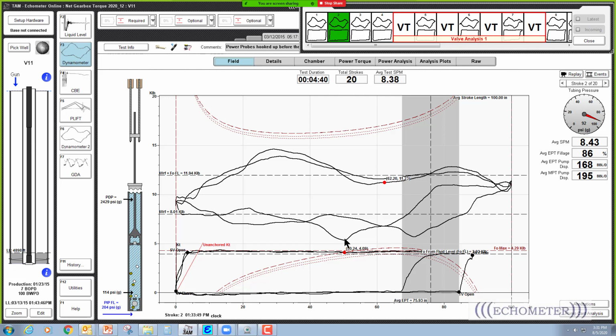So if we set the weights based on a full card, then the gearbox could be even overloaded, but it's probably not, because this load line here didn't cross the permissible load lines. But in some cases, depending on the type of unit, you can get a big negative load or much lower load here, like a Mark unit. All right, so that's to look at different loads and permissible load lines.